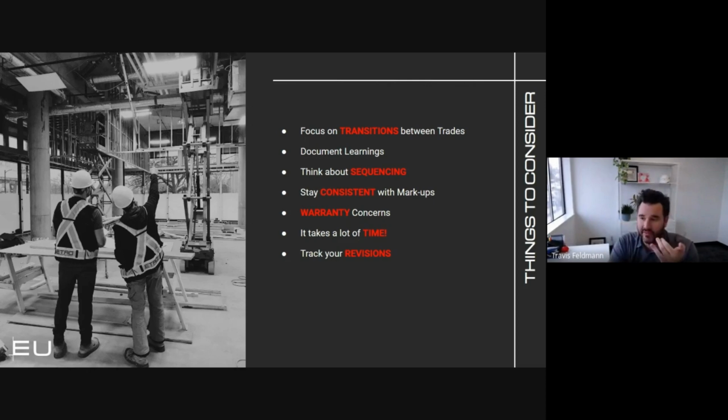You're submitting a ton of RFIs for any gray areas, understanding where the detail occurs, questioning how it's built, clarifying unidentified work, materials or assemblies, making sure you understand where this detail occurs in the project. So making sure that details are clearly identified with grid lines, floor levels, all that kind of stuff. So you're documenting all those lessons learned and capturing that, so then that way when you come up with IFCs, hopefully all that information is in the set.